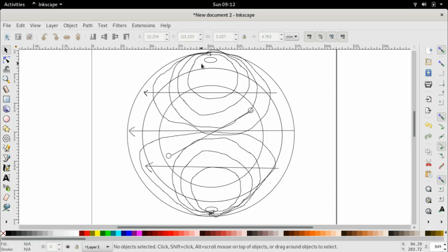I were to look at it as a coil, we already know that the face of the coil in which the current flows in the counterclockwise direction is the north pole where it exits, and the face of the coil where the current flows in the clockwise direction becomes the south pole where the flux lines enter, right? This we already know. So therefore, let us now say that if this is the net stator flux, this net stator flux is now linking with the rotor.